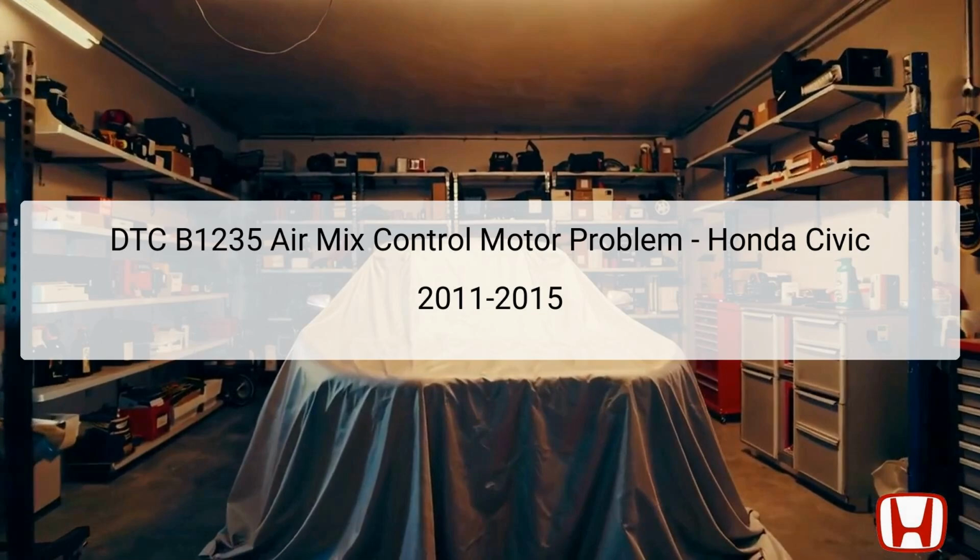DTC B1235, also known as DTC Indicator 42, indicates a problem in the air mix control motor circuit, linkage, door, or motor within the Honda Civic models from 2011 to 2015. The air mix control motor is a critical component that regulates the temperature of the air coming into the cabin by adjusting the position of the air mix door. This door directs the flow of heated or cooled air, influencing the comfort levels experienced by the passengers.